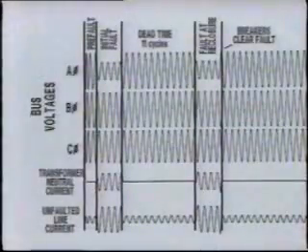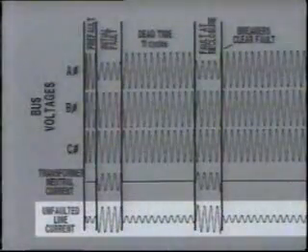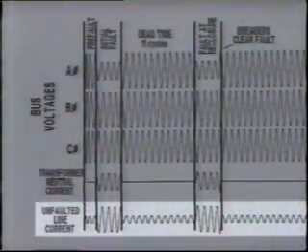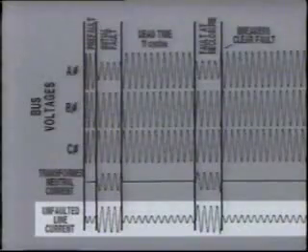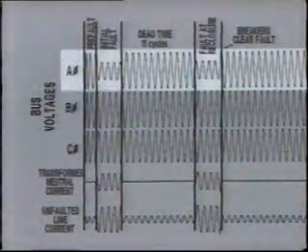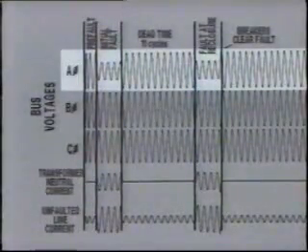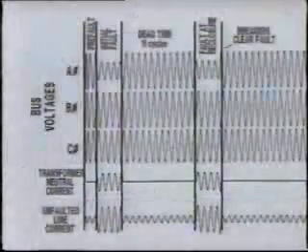The oscillograph system in use here can record 3 cycles of pre-fault data. From the trace of line current, you can see that the line we have monitored is not the faulted line. This is obvious since the current resumes its normal load level after the fault is cleared. From the bus voltages, we conclude that the fault is a single line-to-ground fault on A phase. This is confirmed by the transformer neutral current.